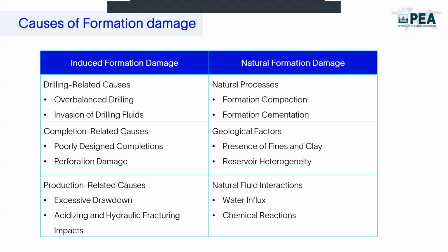If the perforations are not clean, that's why another solution has been implemented: underbalance, to perform perforation and clean up the perforations, avoiding pushing any debris into the formation. Instead, underbalancing pressure will reduce this sort of damage.